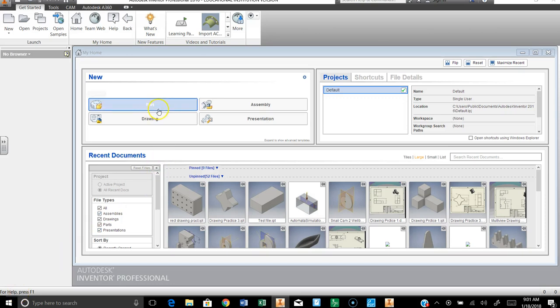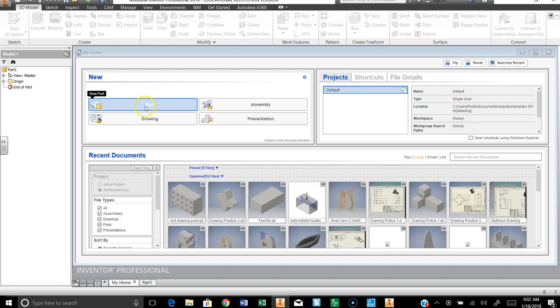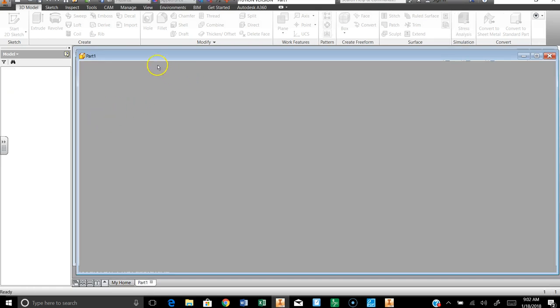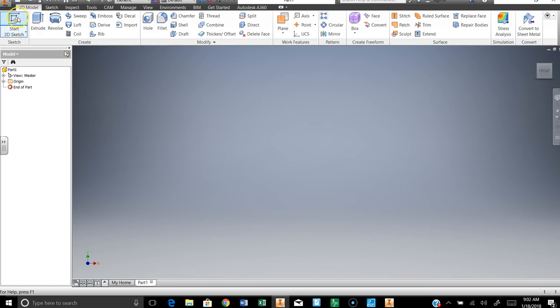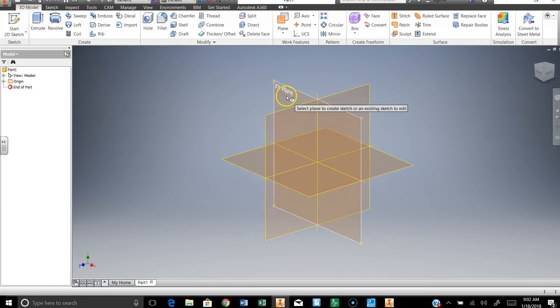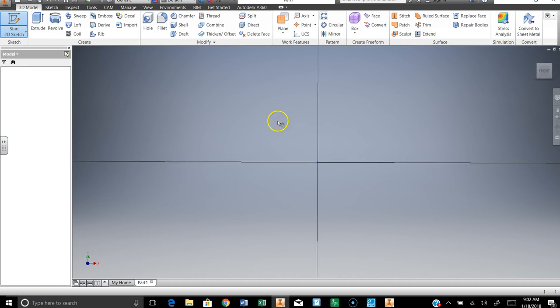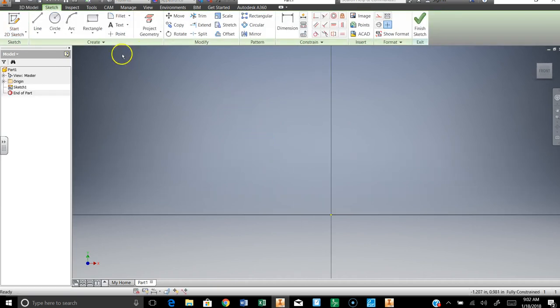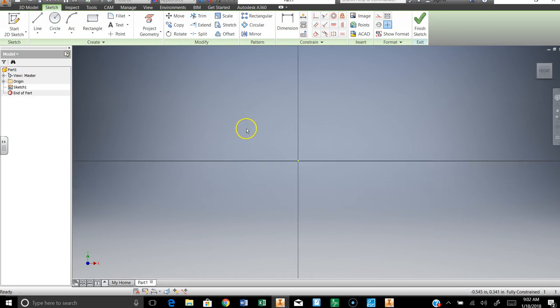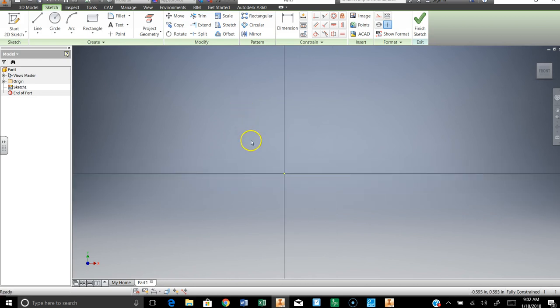So as quickly as I can, I'm going to show you how to make the wheel part. I'm doing this right before the change of classes, so there may be some noise, but you should be able to follow along. So, open up a part, 2D sketch. I like the XY plane, don't know why, it doesn't really matter. Or maybe that was XZ, I don't remember, it doesn't matter. So the wheel is all about circles and arcs, and in fact, we're going to start with an arc.